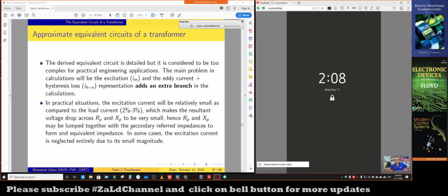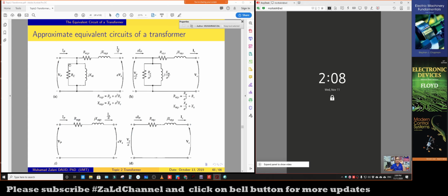This is what we call the approximate equivalent circuit, where RP and XP are lumped together. In a practical situation, we can neglect the exciting current that occurs at this branch, so that we can further simplify.